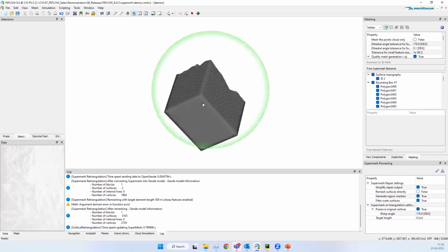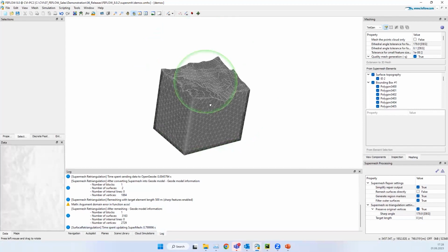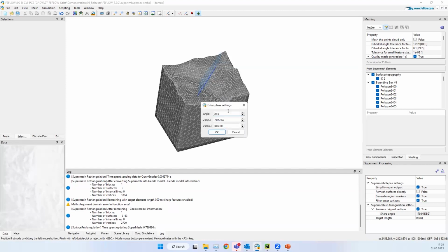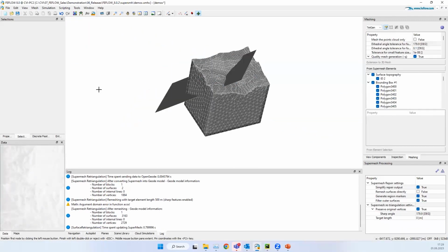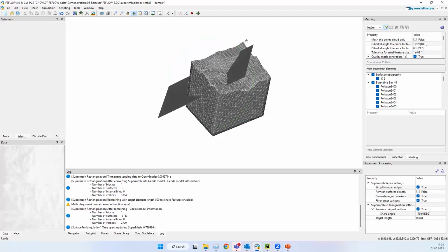Now let's add a fault. Let me go to the top surface, and then I take Add 3D Supermesh plane. Draw a plane; you can press F2 and provide a coordinate if you want. Then this little dialog comes up. Let's give it an inclination of 45. You can also say minus 45, and obviously it will rotate the other way around. 45, and then okay. What you see is it just cutting. I could have extended it laterally completely, but I just did it like this.